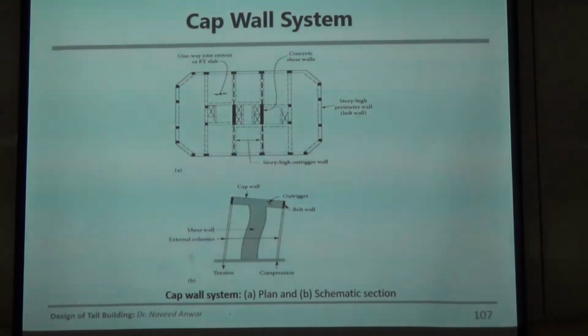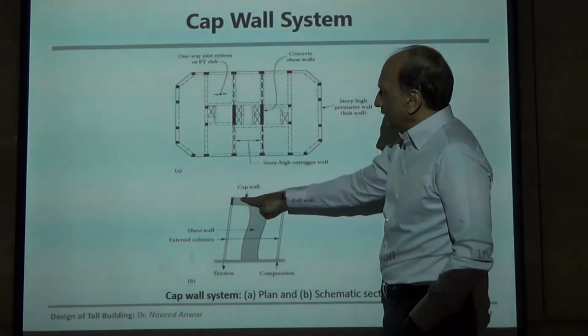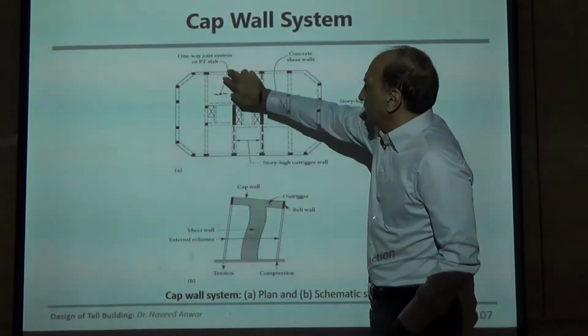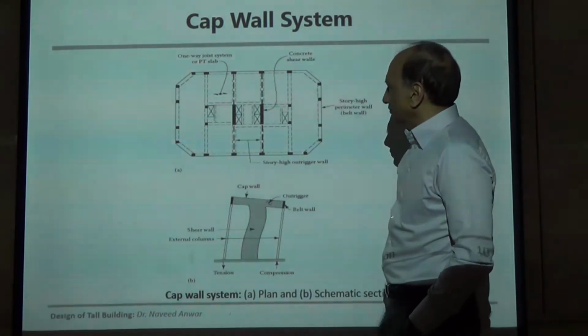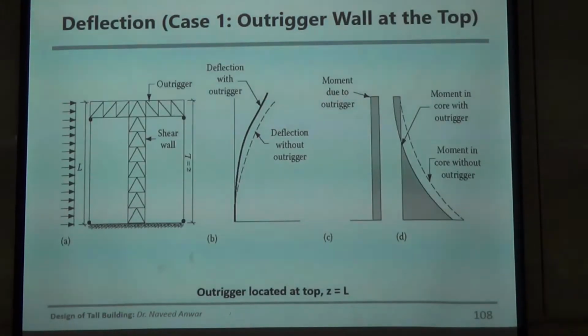So cap wall system, as I told you, cap. Sometimes we can have a cap, and we can put these two as caps on, and then these columns can take it. So caps are also possible, but caps are not as efficient as an outrigger in the middle. This is just a study by someone else; we have done ours in concrete.